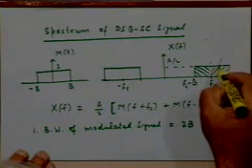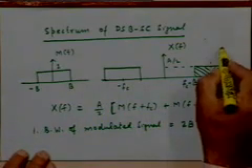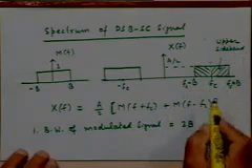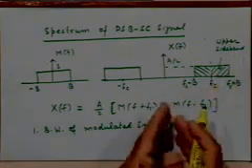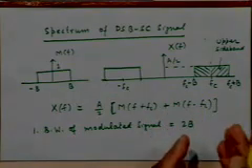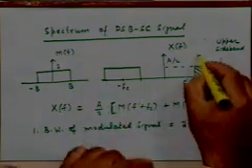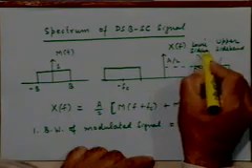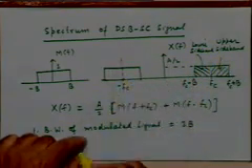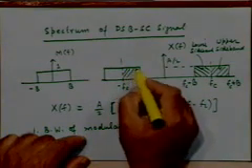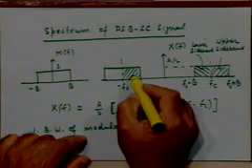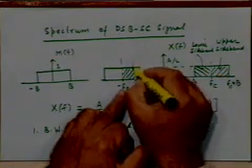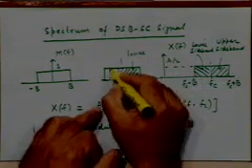You refer to this portion of the spectrum which lies above fc as the upper sideband. So as if the modulated signal contains two sidebands with reference to the carrier frequency, one above the carrier frequency, one below the carrier frequency, and this portion is called the lower sideband. If you look at the corresponding negative plot, this will correspond to which portion? Upper or lower? Lower, right? Because it has to be symmetric. So this will be lower and this would be upper.